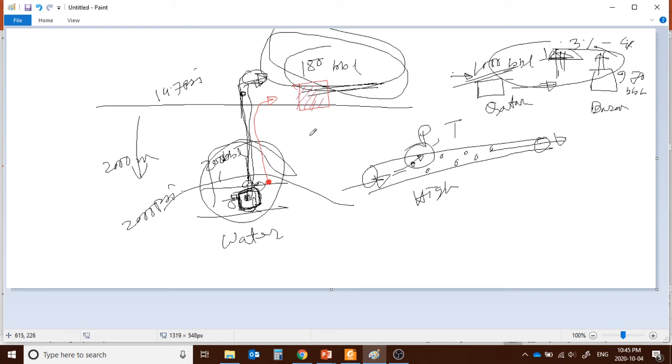Why? Because you are decreasing the pressure and decreasing the temperature, so the volume will be higher. But in the case of crude oil, if you have this amount and take it out, then probably you will get even less sometimes. Why? Because the compressibility of crude oil is lower. Usually it doesn't compress at all. But natural gas can compress in a much higher proportion. Also, it becomes lower because the dissolved gas will go out and vent out. So you will get less.